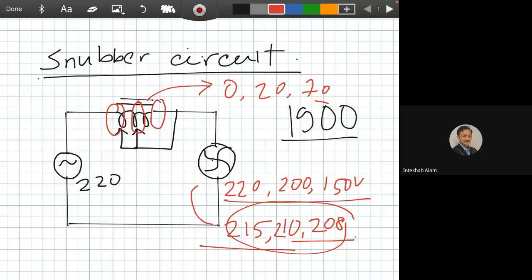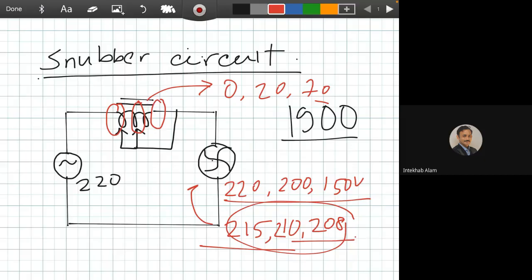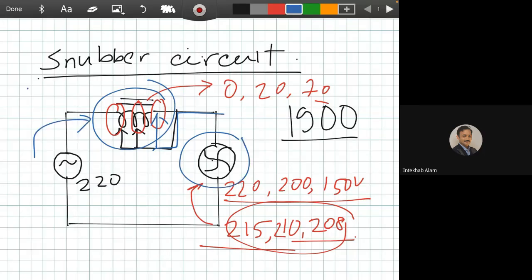But here it was a little bit difficult. There were only 5 steps, in that 0, 1, 2, 3, 4, 5, or some regulators are more primitive, like 3 or 4 steps. Okay. And another thing was that there is a constant loss whenever we regulate the speed. There was a constant loss inside this inductor, and this inductor is an inductive load, and the fan is also an inductive load. So the total AC power becomes a lagging power here.